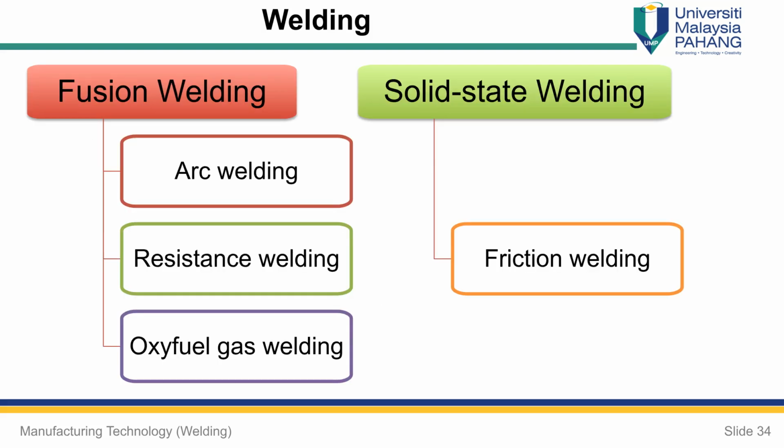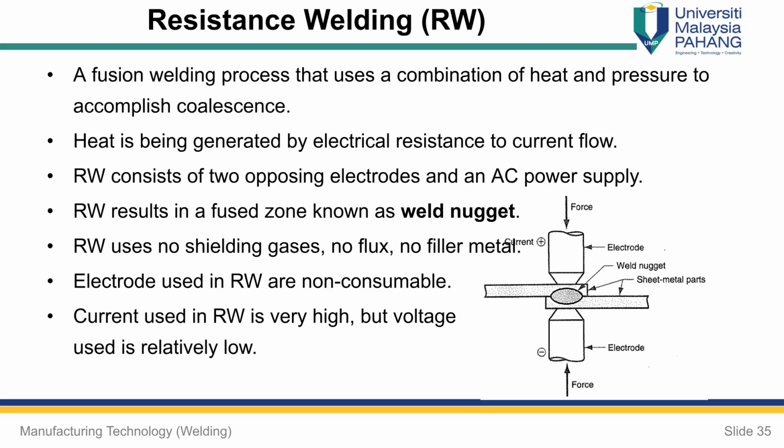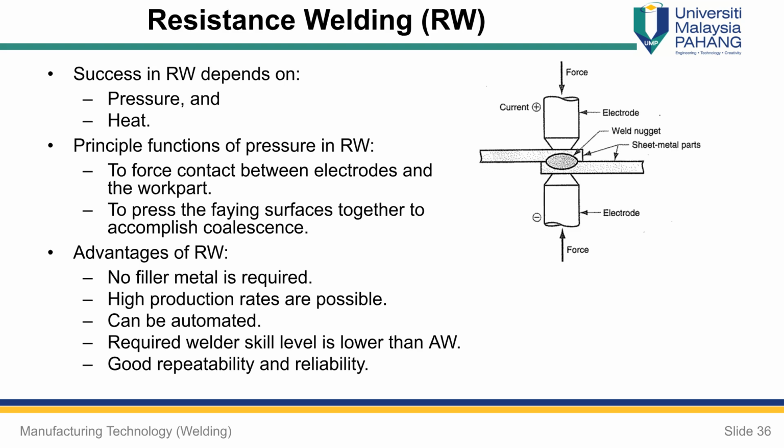Plasma Arc Welding, PAW, is a specialized form of GTAW, where a narrow plasma arc is directed at the weld area. A tungsten electrode is contained in a nozzle that focuses a high-velocity stream of inert gas. This process forms an intensely hot, high-velocity plasma arc stream. Temperatures in PAW can reach 28,000 degrees Celsius or greater due to the constriction of the arc.